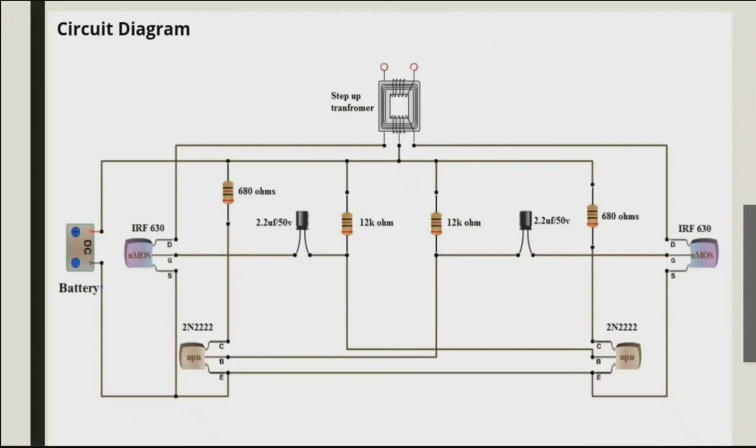In this circuit, R1, R2, R3, R4, capacitor C1, capacitor C2, transistor T2, and transistor T3 will form the oscillator. So each transistor produces inverting square waves. The values of R1, R2, and C1 will decide the frequency, which we need as 50 Hz. The formula of the frequency can be derived.